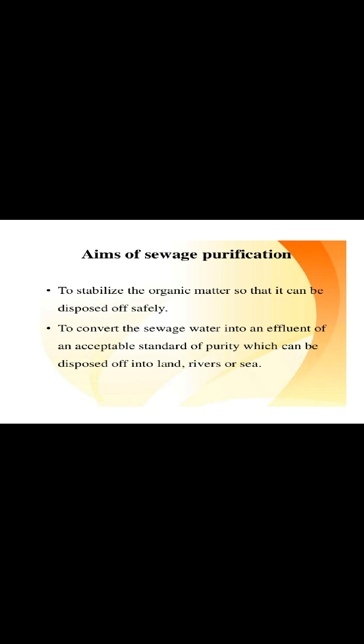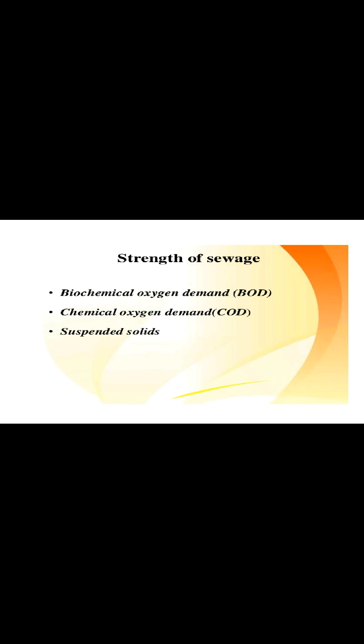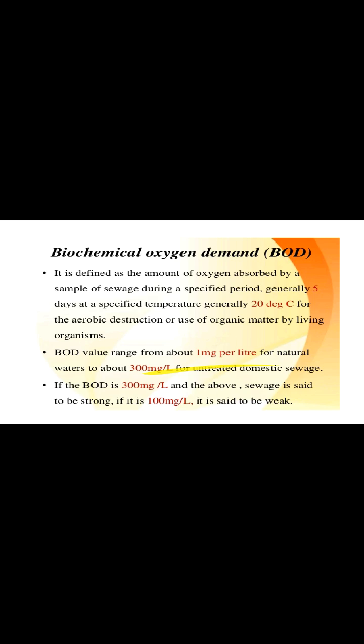The aims of sewage purification are to stabilize the organic matter so that it can be disposed of safely, and to convert sewage water into an effluent of an acceptable standard of purity which can be disposed of into land, rivers or sea. The strength of sewage: the biochemical oxygen demand (BOD), chemical oxygen demand and suspended solids. These are the strength of sewage.